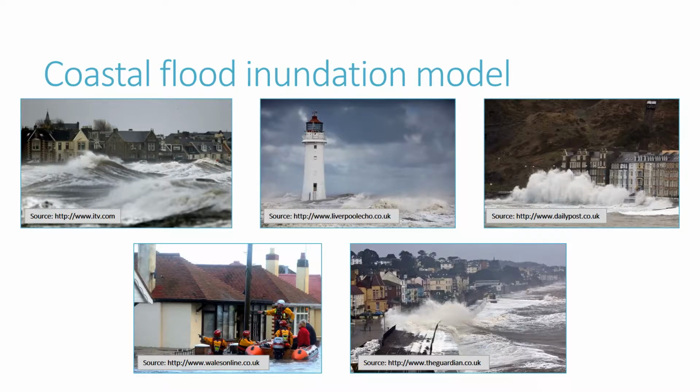Computational coastal flood inundation models can be used to simulate the movement of water over high-resolution topographic data of the land surface. They can provide detailed assessment of flood risk for an area. These numerical models represent tides, waves, currents and surges in coastal waters by solving equations that underlie their hydrodynamic processes. They calculate rates of change of water depth and extent across time and space that will result from different combinations of variables. For example, different meteorological conditions, different tidal conditions, and varying coastal defence systems.